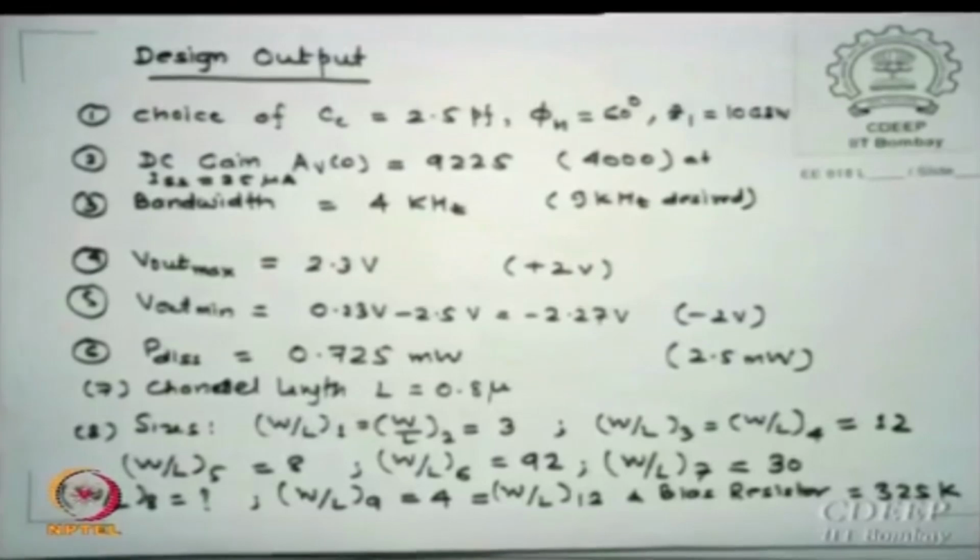Is that clear? If your gain bandwidth point is here, and you put the slope over so much gain, P1 will be very small anyway. So then adjust that value so that your bandwidths are higher. Further reduction is due to CC, because you are improving P2, so you actually moved more to the left side, and P1 became even lower. So that CC can then help you by RZ so that you can still maintain a little higher P1 value.